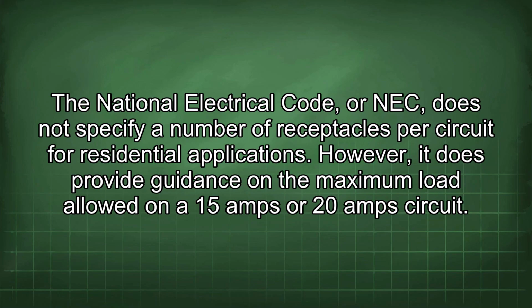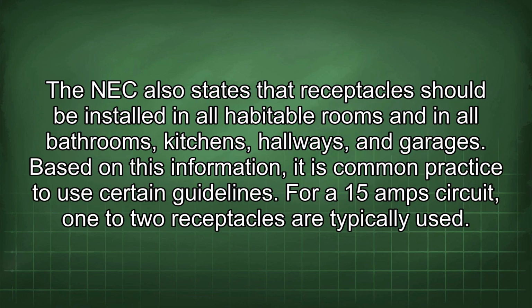The National Electrical Code, or NEC, does not specify a number of receptacles per circuit for residential applications. However, it does provide guidance on the maximum load allowed on a 15 amp or 20 amp circuit. The NEC also states that receptacles should be installed in all habitable rooms and in all bathrooms, kitchens, hallways, and garages. Based on this information, it is common practice to use certain guidelines.